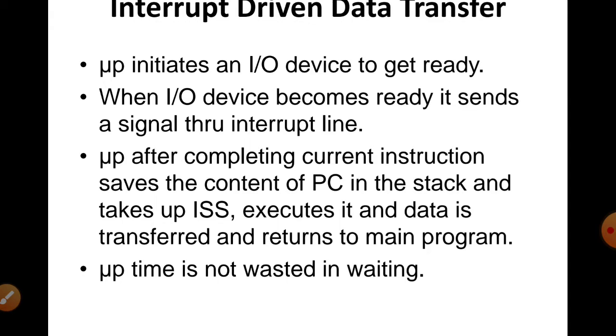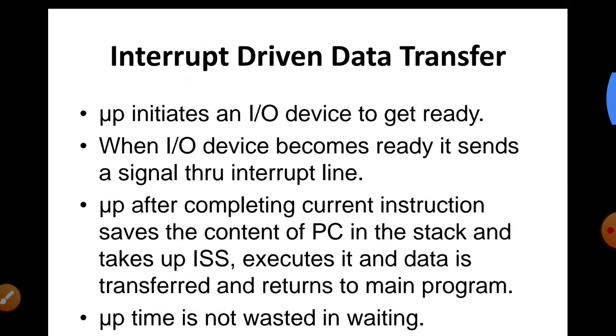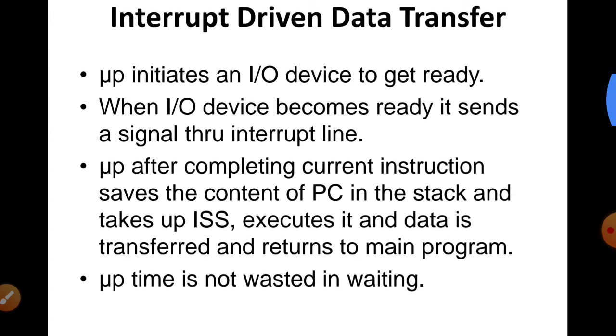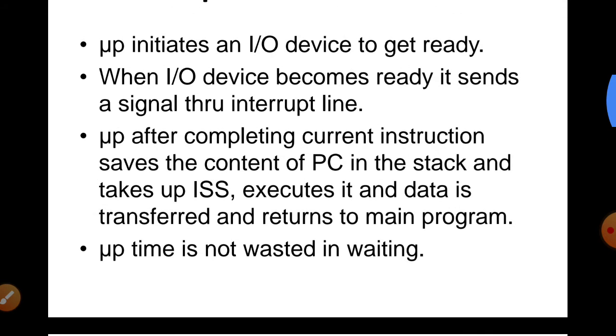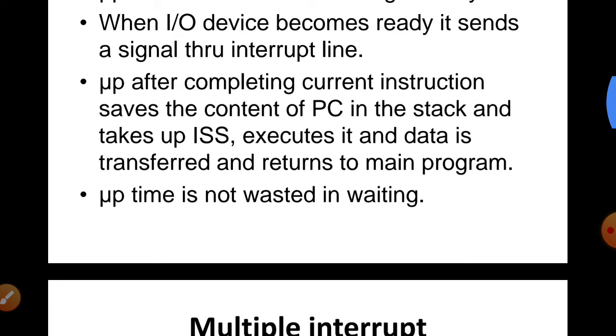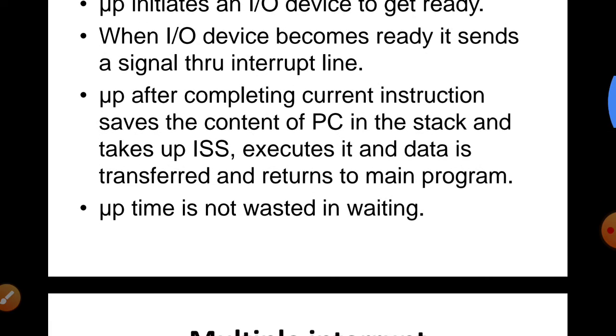Now the microprocessor can ignore or delay the maskable interrupts if it is performing some critical tasks. However, it responds to the non-maskable interrupt immediately. In many ways you can take an analogy of a telephone kept off the hook, and it is ringing, but if you are doing something, whenever you are interested, you will take the message.